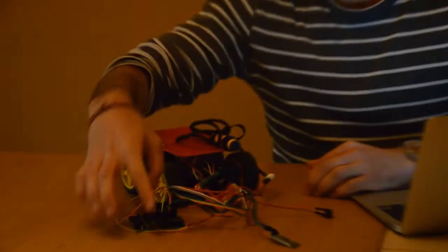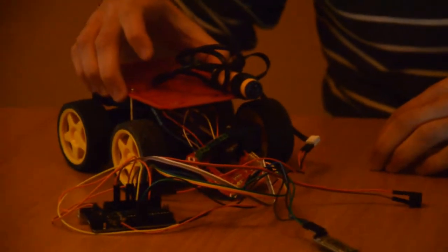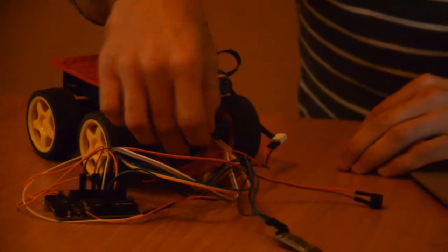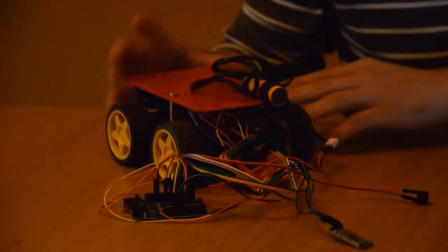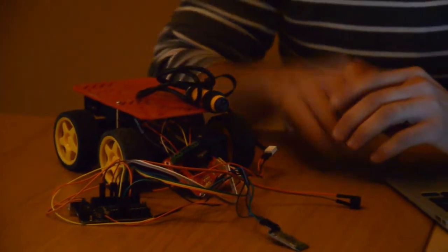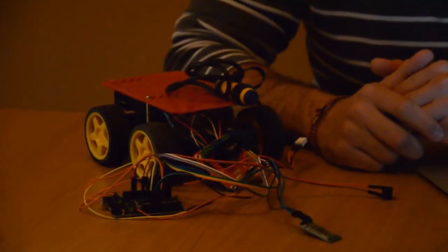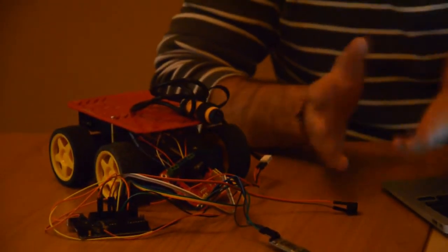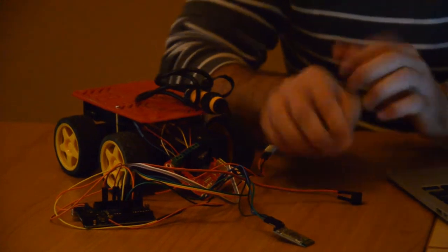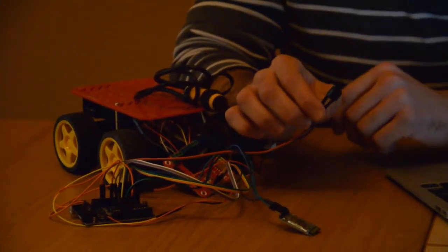First, we have an Arduino Uno, a card with 4 motors, and an H-bridge used to connect the Arduino with the motors of the car to transfer the power and to set the directions in which the wheels will rotate. We have a proximity sensor for object detection, a Bluetooth module used to transfer orders from the mobile application to the Arduino, and a buzzer which is used as an alert for the user. All these components are powered by an external source, a small battery, and that's it.